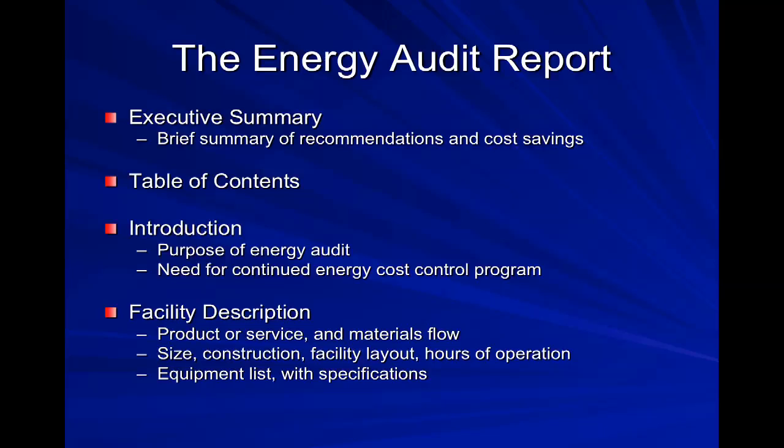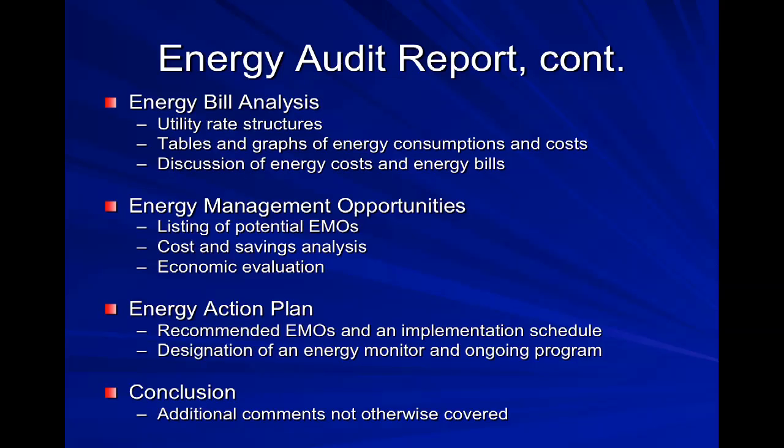And so again, we have to have an introduction. We have to describe the facility and all the equipment. We have to analyze the bills, list possible energy management opportunities, and not only what it could save, but how much it makes sense. Yes, it might save us $10,000 a year, but how many years will it take to recover that savings? The investment may outweigh the potential savings. So we have to come up with a plan based on all this data that we've collected and make some sort of a conclusion that wraps everything up.